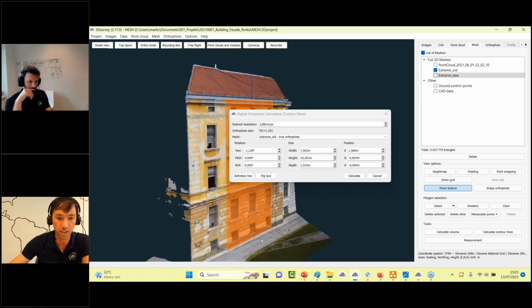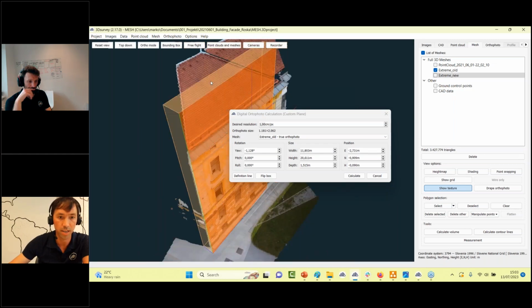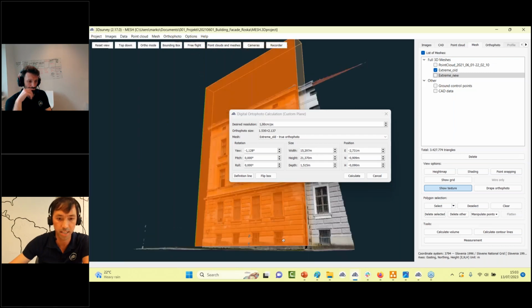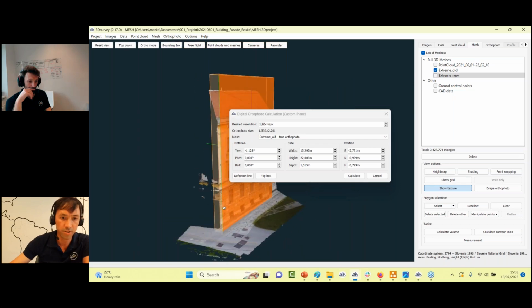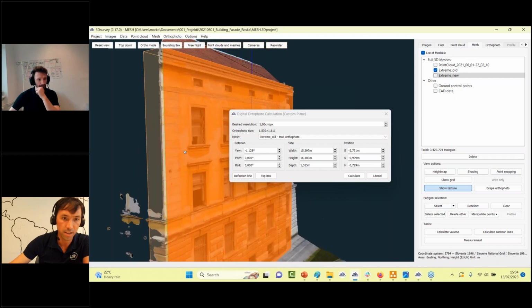Then you can improve this position with the right mouse click on a plane of this bounding box, like so, and so, to extend it. Also on the right side, also on lower, a bit down. If you're just interested in facade, this would be good enough, like so.